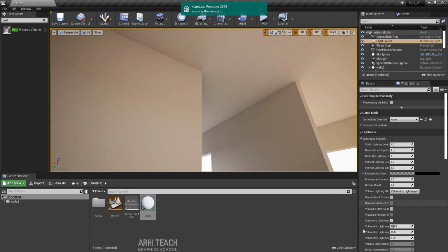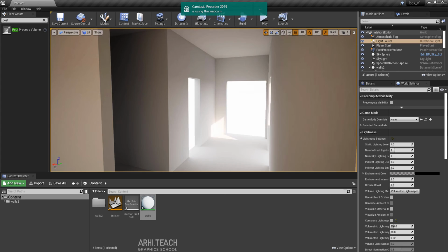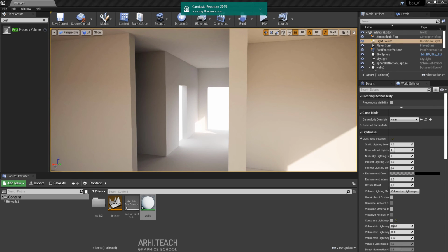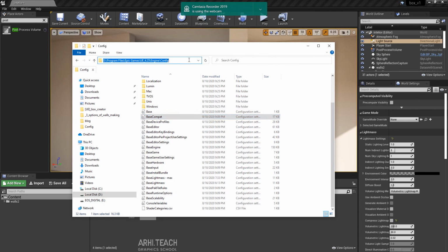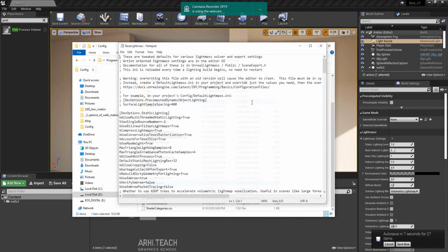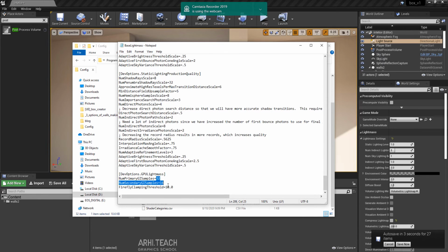First of all, make sure that the Compress Light Map checkbox is unchecked. Then there will be no light map compression. And second, we go to the light maps configuration settings. Disk D, program files, Epic Games, your current version that you are currently running, engine, config. Here we need to find light maps. So I had the lowest settings, which quickly show the result.